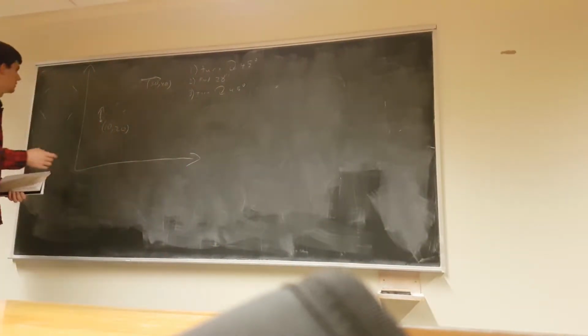How do you do this? Well, you can figure out how to make this kind of drive turn on the spot. You send that wheel that way, that way, that way, and that way. The robot will turn, right? So assume this is just one output, where you're sending the same value to every wheel, and your input is maybe the position of one of the wheels. You've done the math based on the radius here. You know how far the wheel has to turn to get the robot to turn 45 degrees. So you now have a target for where that needs to be. You have an input, and you have enough to build up a PID loop for that, right?